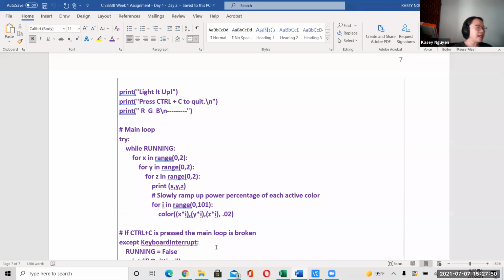Okay, so when you plug it in, spread out the legs for the RGB and make sure that you follow the schematic that's provided to you. And then you can leave your Raspberry Pi on when you're plugging it in, write your script, run your script, look at your shell to see the output, and look at your LED. If it's not flashing, then possibly you plugged into the wrong pin, okay? Or maybe your LED is flipped around somehow. It's not having the right connection.